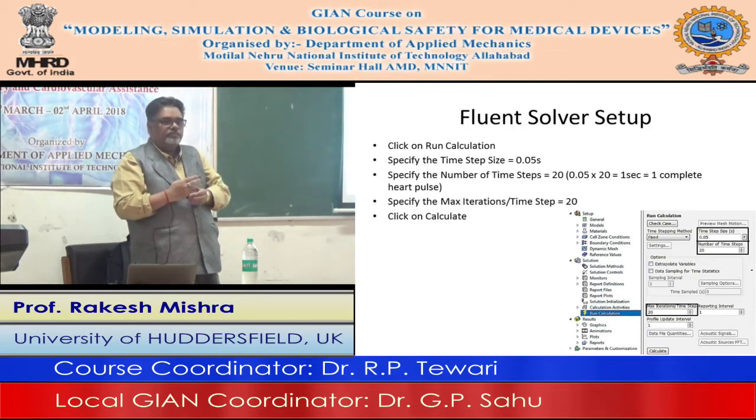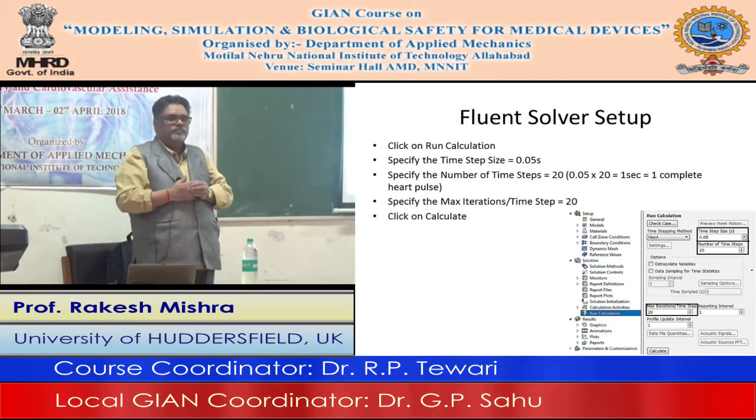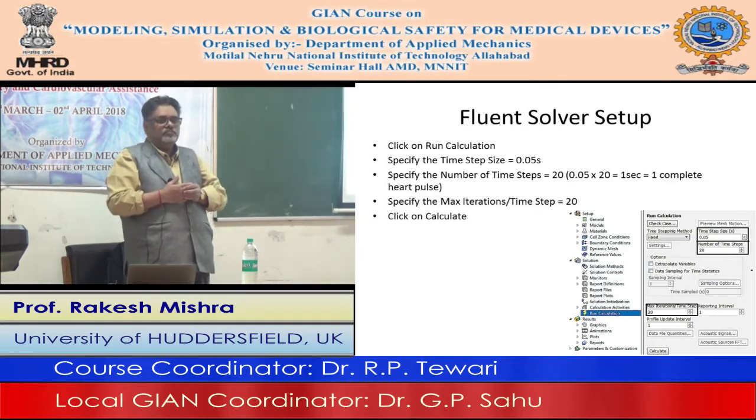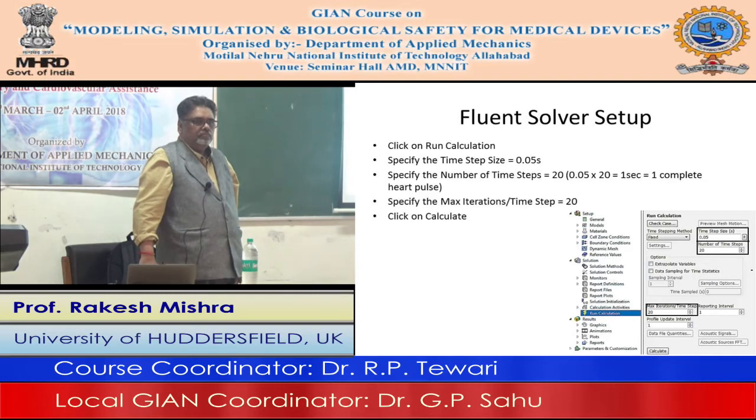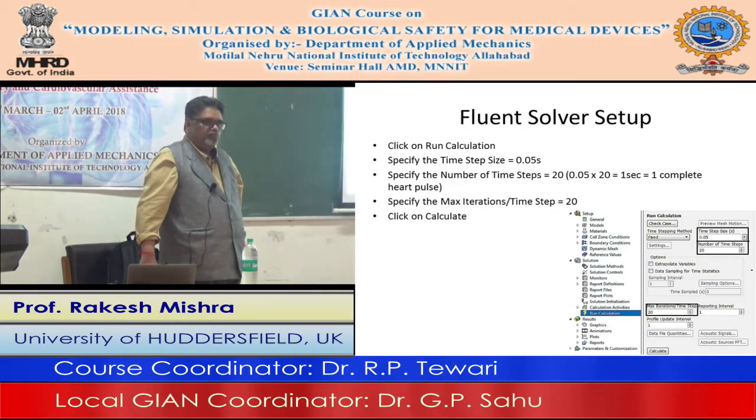We studied this case, and we are running the transient simulation with the UDF. The time step size is reaching 10 to the power -5. If you are tightening the residual from 10 to the power -4 to 10 to the power -5 and -6, the time steps are also decreasing, going from the macro level to 10 to the power -6 or -7. In that case, there is a need for time independence because we are also running at the micro level.